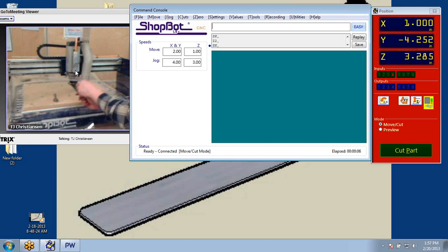There's a groove on the shaft, and then there's a groove on the collet nut. I'm just going to bring these together, loosen it up. And this is where you want to watch. If you're a big gantry tool and you're doing this at the corner and it drops, it's going to drop down and hit the concrete and wreck the tip of your bit.